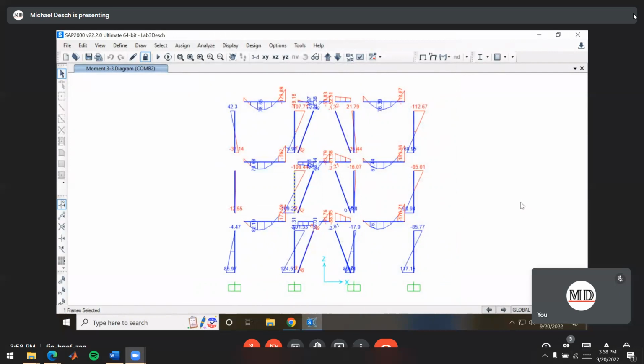Okay, so make sure you include your screenshots of all the shear diagrams here, as well as let me know what your max moment is. Same for shear diagrams. Include each of the story drifts for load combination 1, combination 2, and their ratios. So that's 9 numbers in total. Also your displaced shape and your reactions. And when you're doing them, make sure they're for the right combination that I'm asking for, because there are 2 of them. So make sure it's the right one.